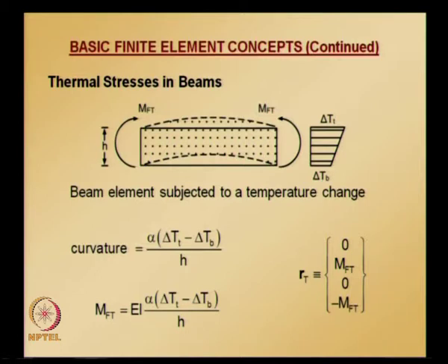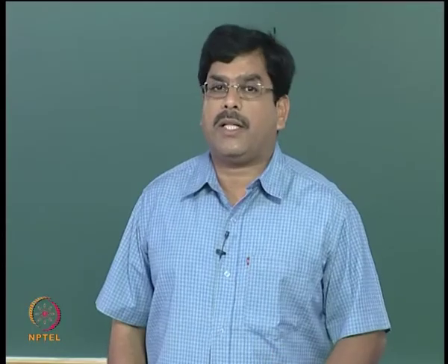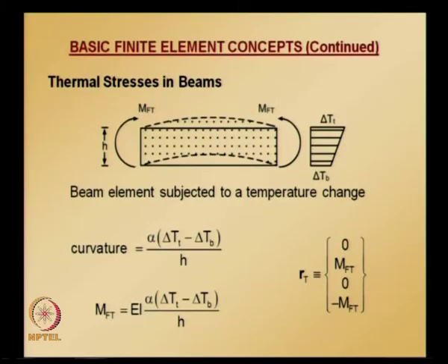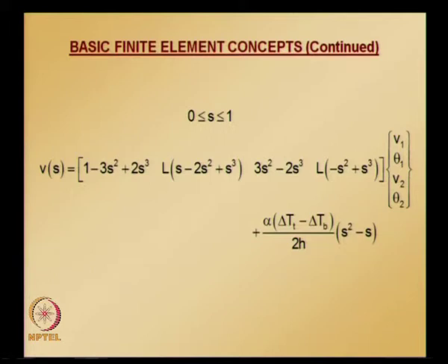And once we get these values, we can go back to each element, and since the beam is subjected to thermal stresses, it is subjected to uniform moment, so we need to apply a fixed end correction to the final solution that we get from finite element. Let us see in detail all the steps by taking an example.